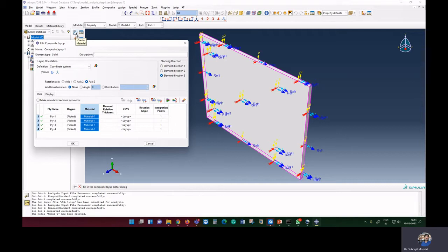So here I want to apply the material property for all the layers so that I can check whether our frequency comes out the same or not. Whether we can consider 10 mm thickness as a single solid element, or we can consider 4 layers of 2.5 mm, and whether we are getting the same frequency or not. So here we are going to check whether 4 layers of 2.5 mm and 1 layer of 10 mm give the same result or not.